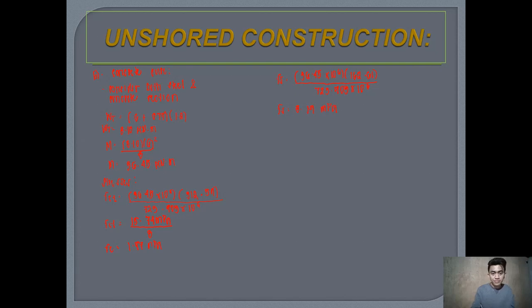Now for short construction, what are we going to consider? Right here, summary. For summary, the stress in concrete will be this one. I have here 1.97 megapascal. And then for the stress of steel, we are going to add now Fs from concrete cure and then Fs from concrete wet.